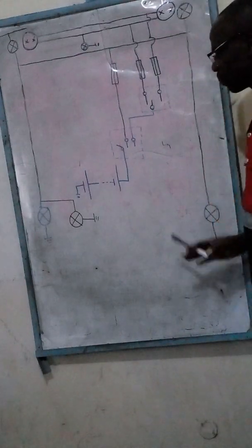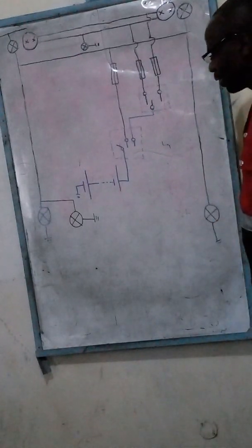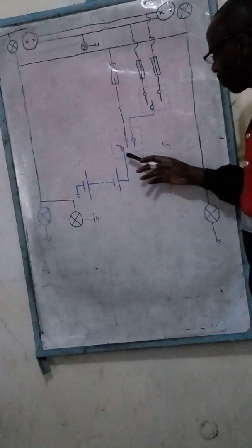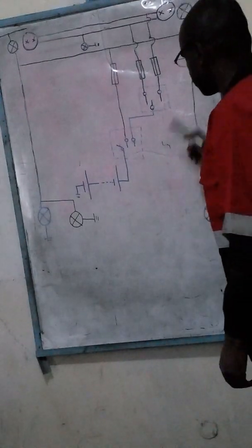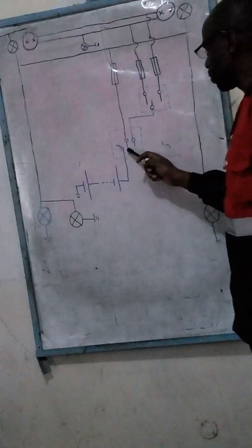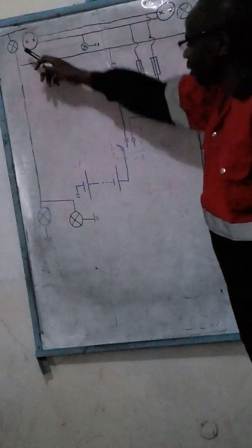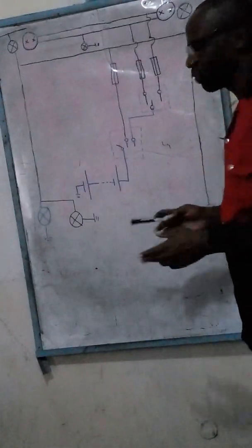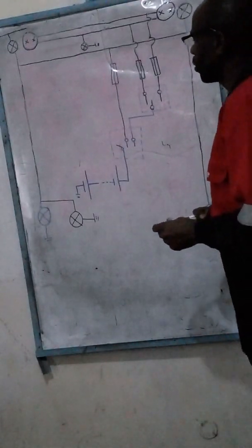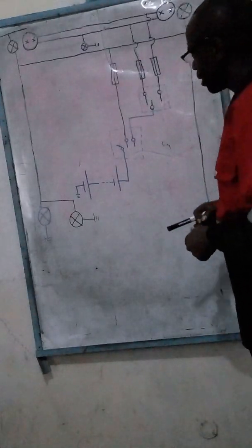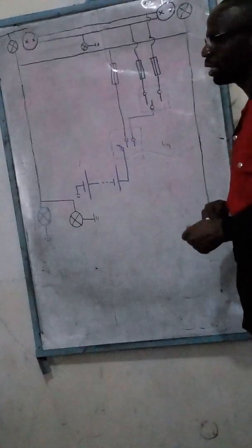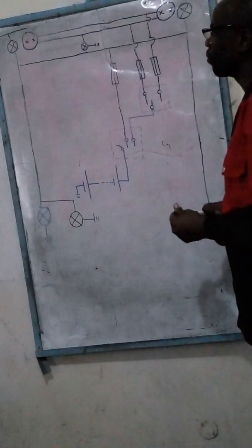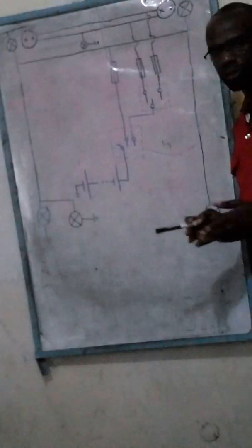The operating principle is simple here. Current flows from the battery to the headlight switch, which is a multi-stage switch, as I said a few moments ago. At the first stage of the headlight switch, we are connecting to the park and tail lights, and these lights should have a wattage of about 5 to 7 watts. The park lights and tail lights are normally used at dawn or at dusk in order to improve the visibility of the car from all other directions for other road users.